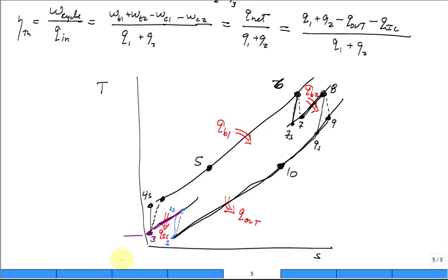Those 4? Okay. Now the other thing is, if you wanted to, you could sometimes show that this heat goes to that warming. Going from 9 to 10 is a cooling in that regenerative heat exchanger, and that provides the heating from 4 to 5. But that's internal to the cycle. These are external: out, out, in.